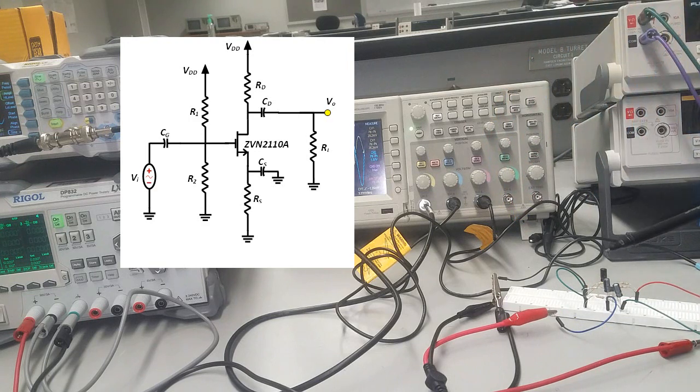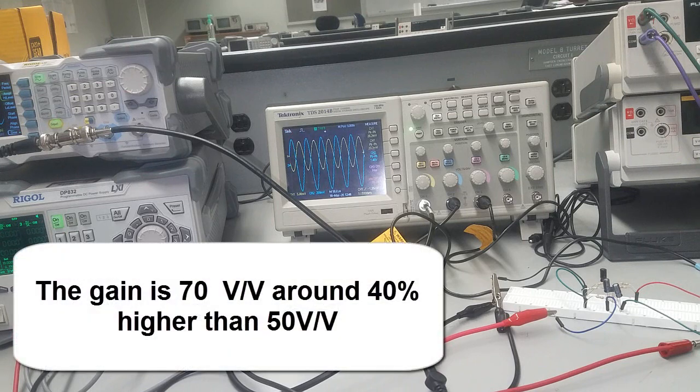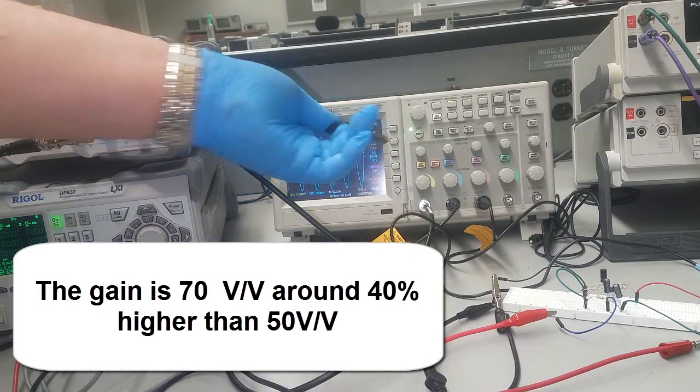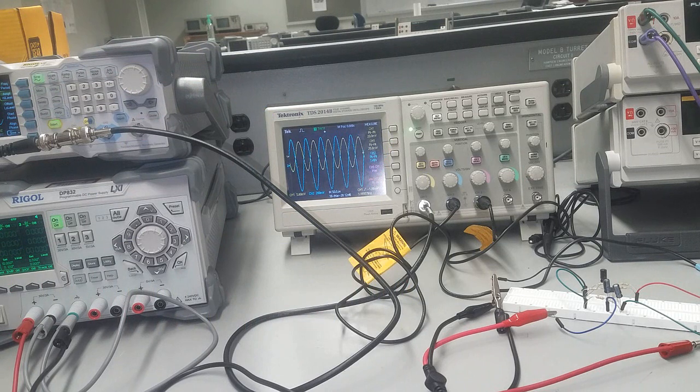You need to do that, otherwise the capacitor will pop. It pops if you reverse the polarities, so pay attention to that. Anyway, when we investigated, the gain was a little bit higher than expected, with about 40% tolerance. You can see that the voltage at the output is 1.4 volts for 20 millivolts input. It should be roughly around 1 volt to get a gain of 50. So we need to lower the gain.